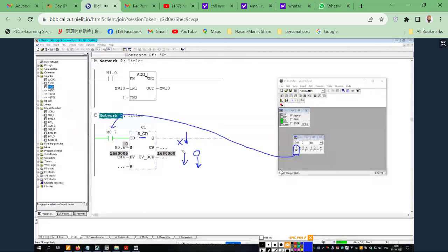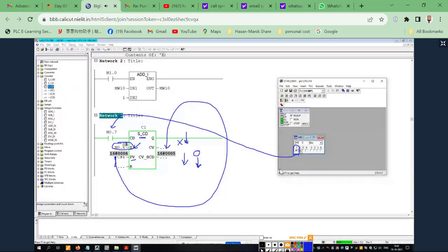So then how to do it? This operation, countdown, then you see this is the set switch. Once you press the set switch, the preset value, PV, is loaded to the accumulator value. You see, just I press the button, 6th button, you see, this is the value. And now maybe you are thinking, sir, what will happen? Here actually it is 6, right? Now it's loaded to store.